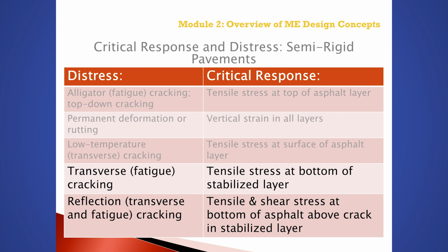The tensile and shear stresses at the bottom of the asphalt layer above the crack in the stabilized layer are used to predict both transverse and fatigue reflection cracks.